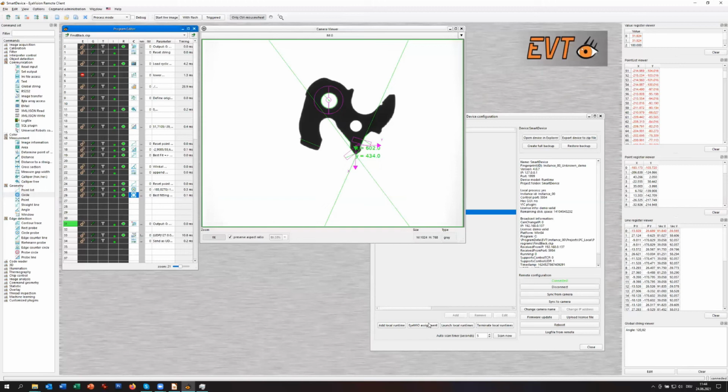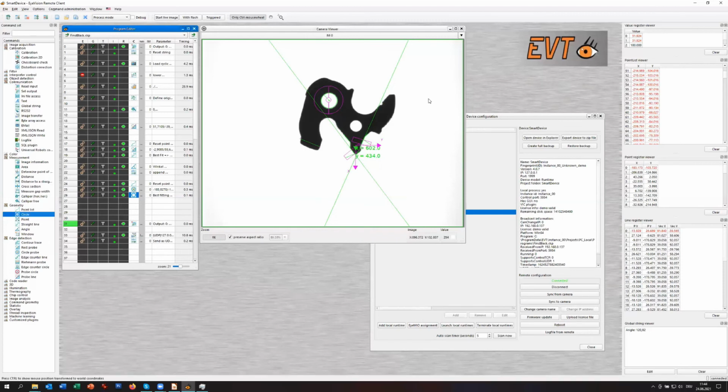Right now we are not calibrated, but I know it's repeating always, you have these calibration tools here in the iVision software, and if you want to measure calibrated, you simply use the calibration tool to calibrate your field of view. You can also do the distortion correction if you don't have the best lens.